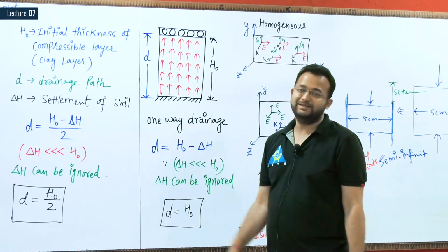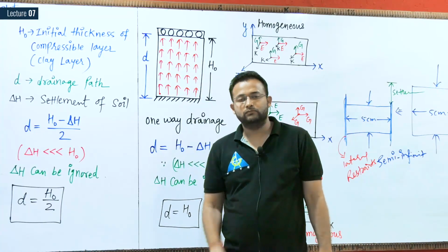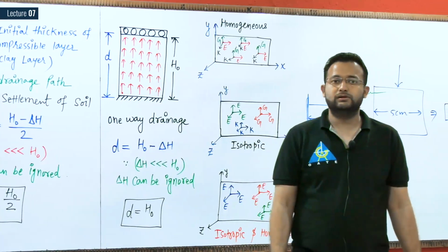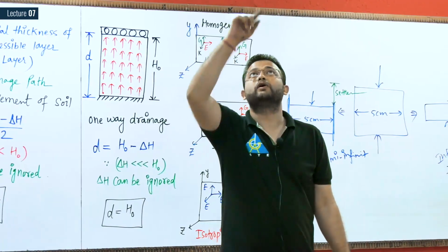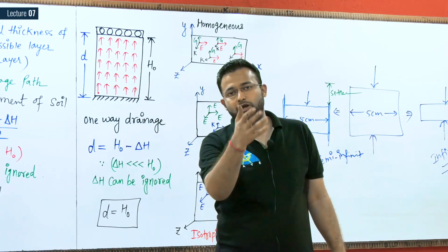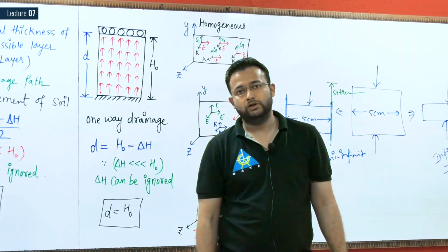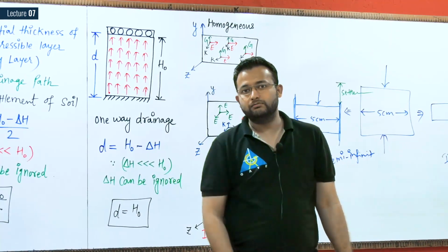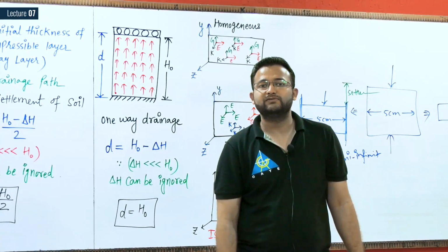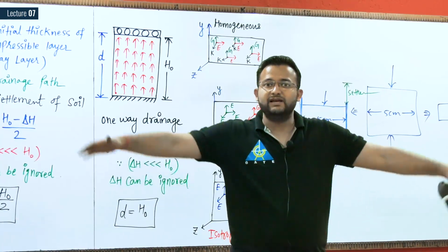So your soil should be semi-infinite. Why? What is the reason why we are doing like that? Because when I construct the footing, because of footing, load is applied in vertical direction, and the soil present below the base of footing gets compressed. So this depth direction is finite for me, but this lateral direction is infinite for me.